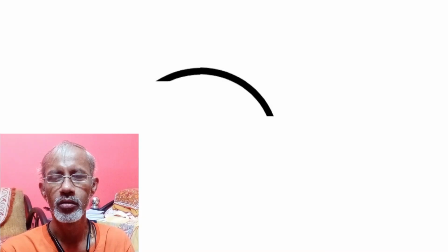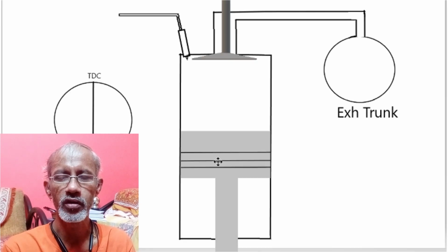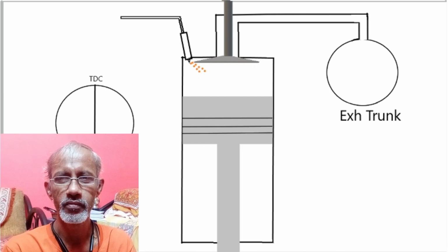So to increase the amount of fuel before the piston reaches the TDC, we'll have to make sure that a portion of the fuel which is being injected after TDC has to be shifted over to the piston movement before it reaches the TDC.